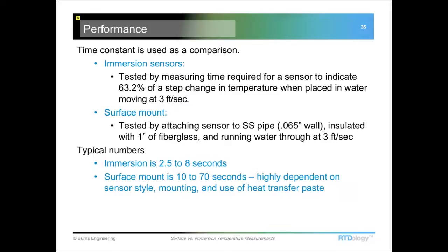Yeah, there are a few different types out there. The one that I like is a silicone oil-based paste that has a ceramic powder mixed in with it, and it's used a lot for heat sinking integrated circuits on a circuit board. It's got a really wide temperature range, and you can put it on a surface and get it up to its max temperature, which I think is about 200 C, and it won't run or drip or separate out.